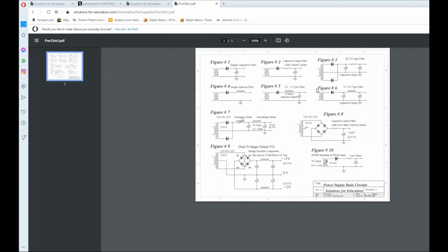It was a hefty thing. I mean, you're talking about lots of current, lots of voltage. What happened is this coil was shorted to the frame of the power supply. And because it was shorted to the frame, here's what happened. The techs on board the ship were trying to find out why this power supply kept throwing the breaker. And they couldn't figure it out.